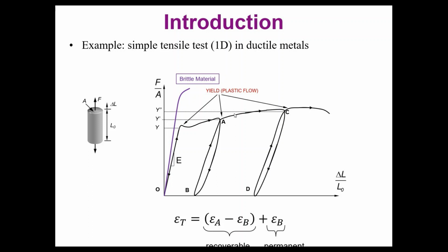So this is a much more powerful model than the isotropic linear elastic model that we commonly use in civil engineering. It's simple, it's very effective. It's still a model that is isotropic, so we are not capturing different behavior in different directions. This could be a limitation, for example, when you run models in soils, because we know that soils are not isotropic, but as a first model to use plasticity it is a very good model because it's simple to understand and it's very powerful indeed in comparison with the linear elastic model.